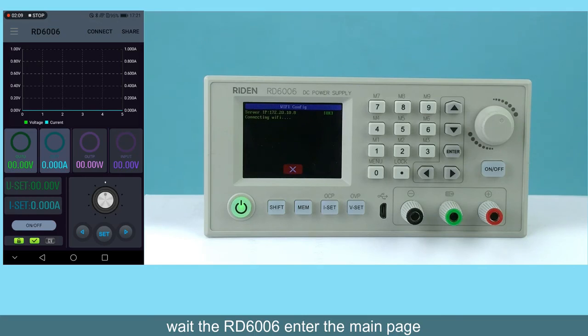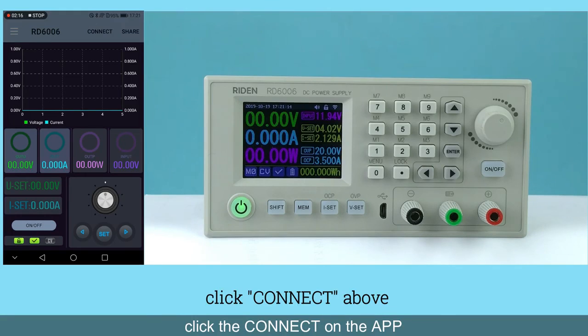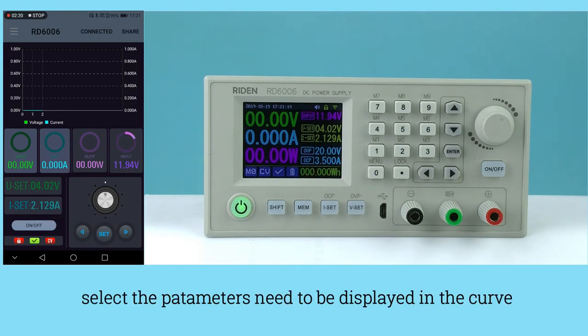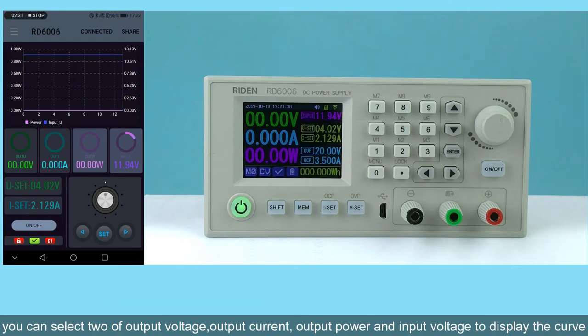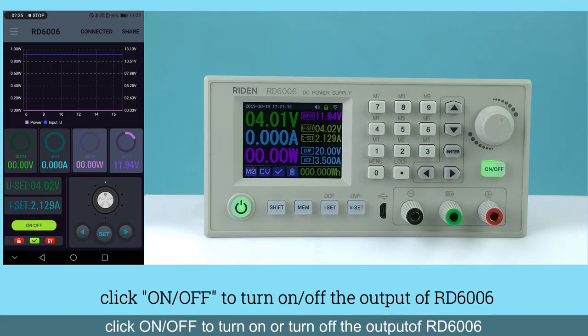With the RD6006, enter the main page. Click Connect above. You can select two of output voltage, output current, output power, and input voltage to display the curve. Click On/Off to turn on or turn off the output of the RD6006.